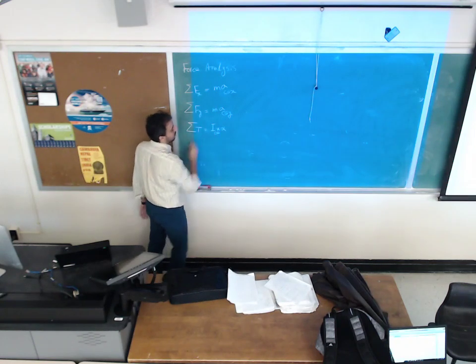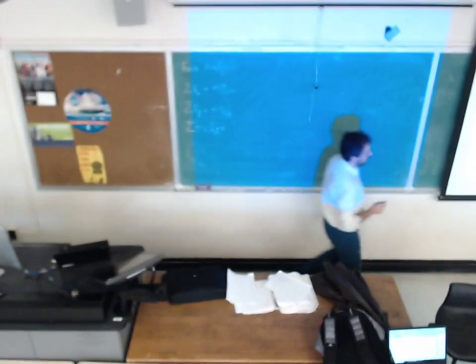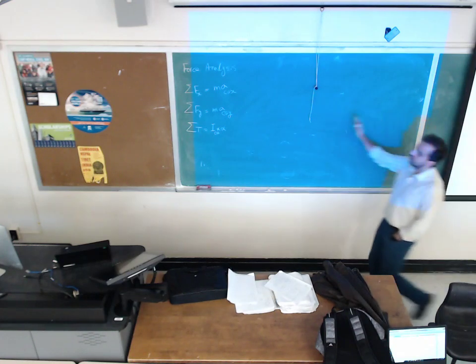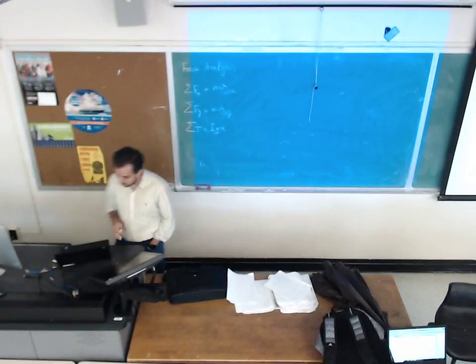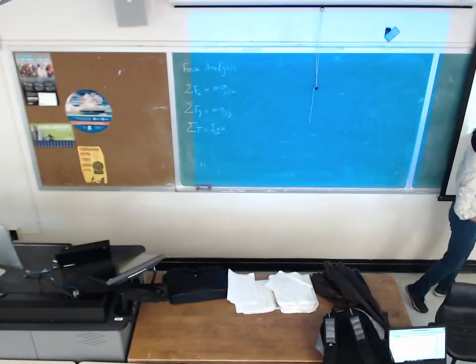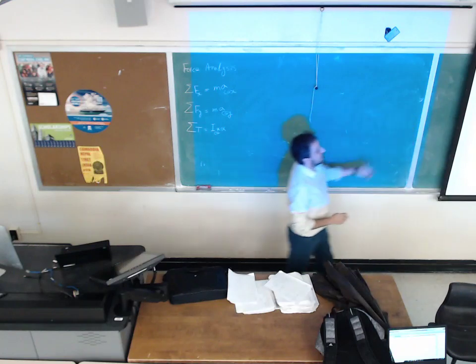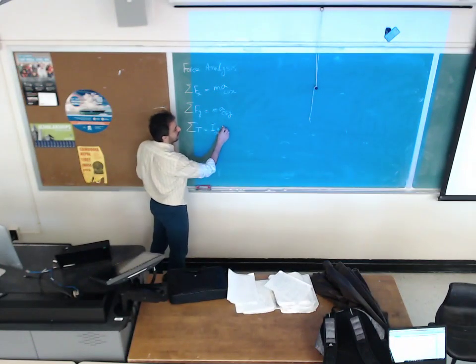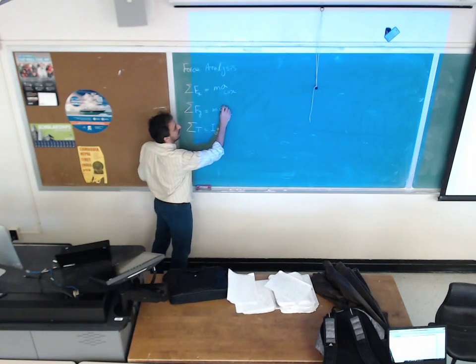So when we want to do this force analysis, first of all, we should be done with the kinematic analysis. I mean, displacement, velocity, and acceleration should be done. If we do that, we can find alpha, the acceleration of center of gravity in X, and the acceleration of center of gravity in Y. Then we can start force analysis.